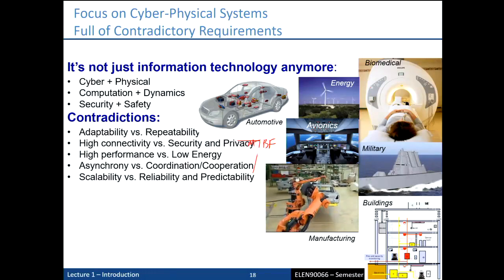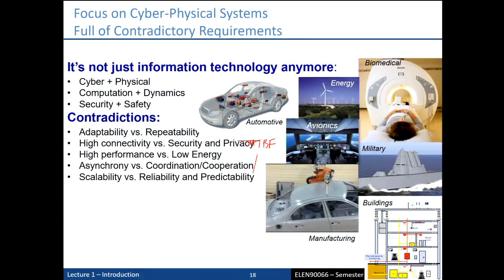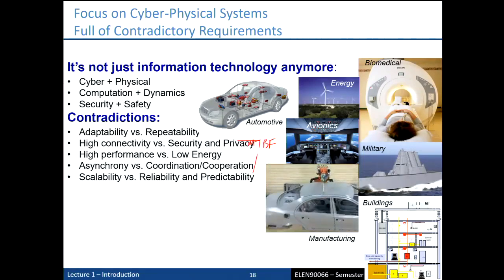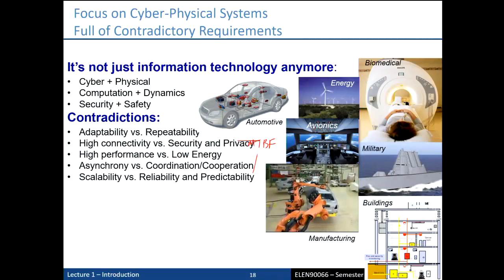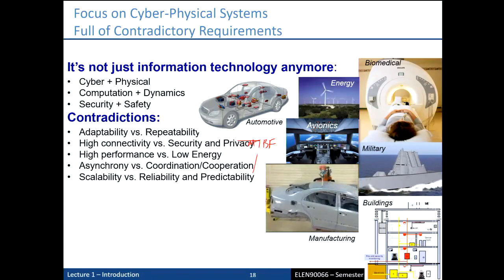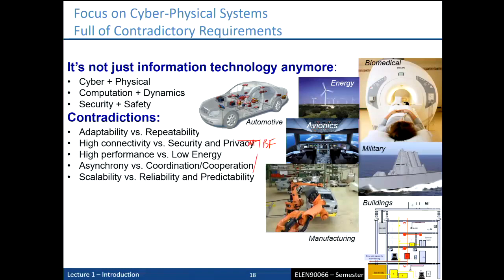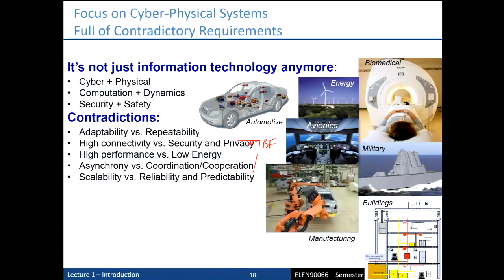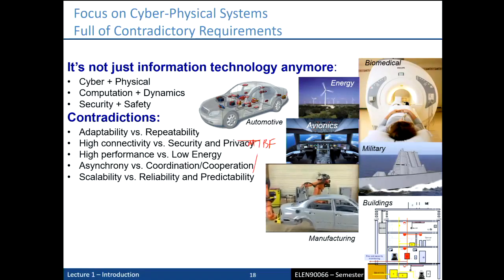And that is related to, obviously, how well it's put together, but it's also related to how many units are out there, right? If you have a mean time between failures of a certain amount, but then you pump a lot of those units out there, you think statistically, okay, there's the mean. It might be normally distributed, where the mean time between failures is some point. But the more you get out there, the more likely some will fail early. Okay, so we have scalability. You start pumping lots of stuff out there, your mean time between failures could go right down. Or do you just really restrict it and only put a few out there and you can live with perhaps no failures or very predictable behaviour?